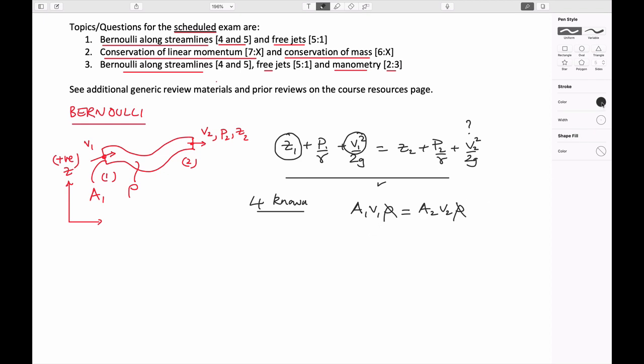So that applies within the flow field. We know that we can use this to calculate the behavior of free jets. If we have velocities, then we can look at solving along a streamline for the behavior that we would have if things are airborne. The requirement is that we know the exiting velocities, Vz and Vx.